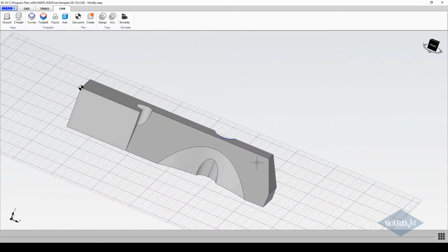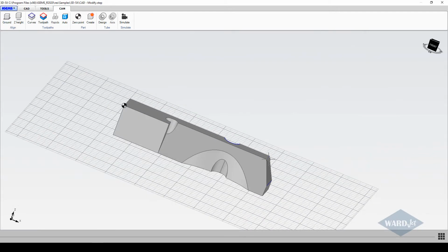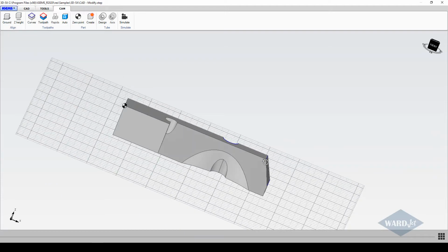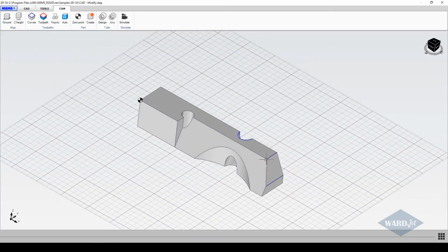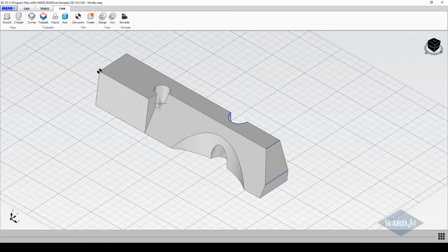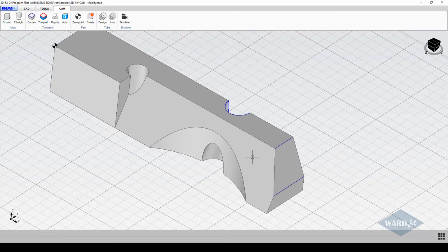And then when we start, probably want to start somewhere off the edge, or at least over here somewhere. Because if we start our pierce here, the jet's going to want to be basically projecting along this edge here, and then it's going to be tilting as it's going along, and probably won't look that great.